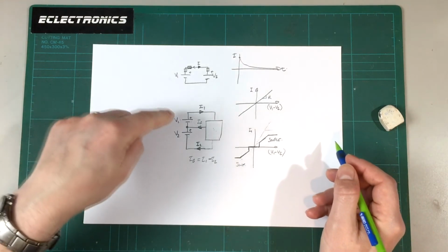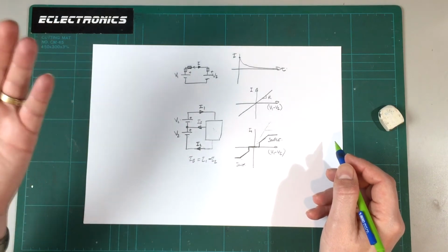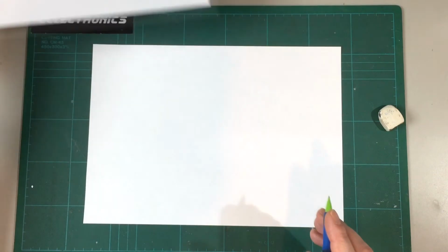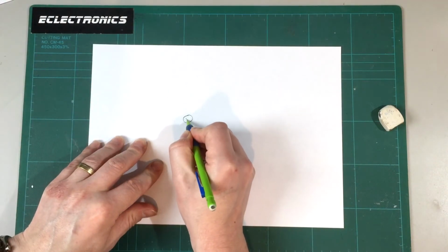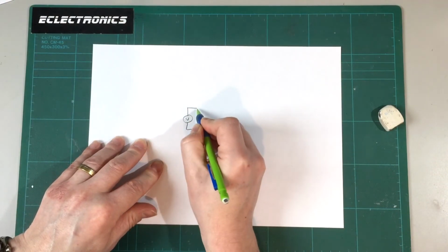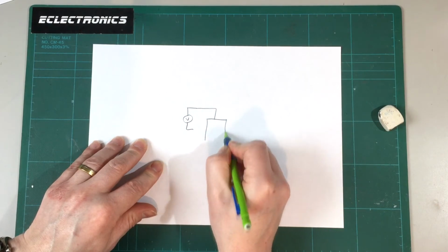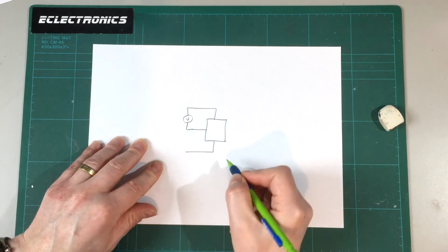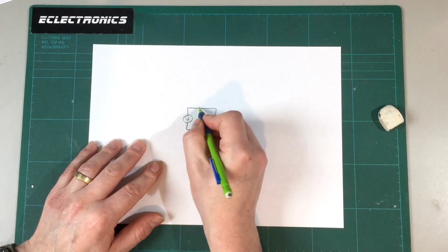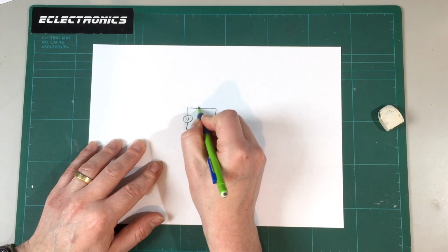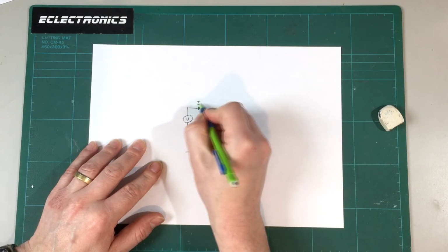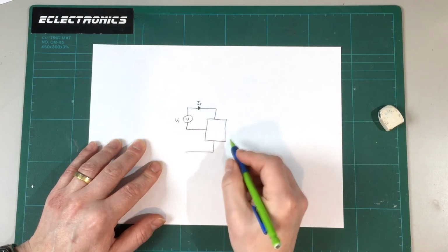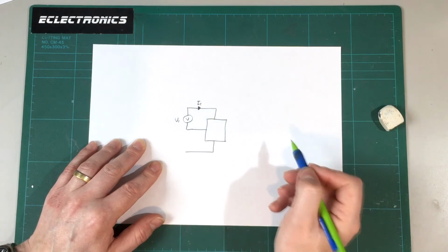So I was thinking maybe there's a better way of doing this. Could we make one of the cell's voltages fixed? Well, the answer is yes. We could substitute that cell with a power supply. So if we take a DC power supply, that represents one cell in our balancing scenario. So here's our balancer, like that. We can have a power supply which can only supply positive current because it's a power supply, it doesn't sink current. So again, V1 and I1, it can only supply positive current. So we're only going to measure one quadrant having the power supply in that position.